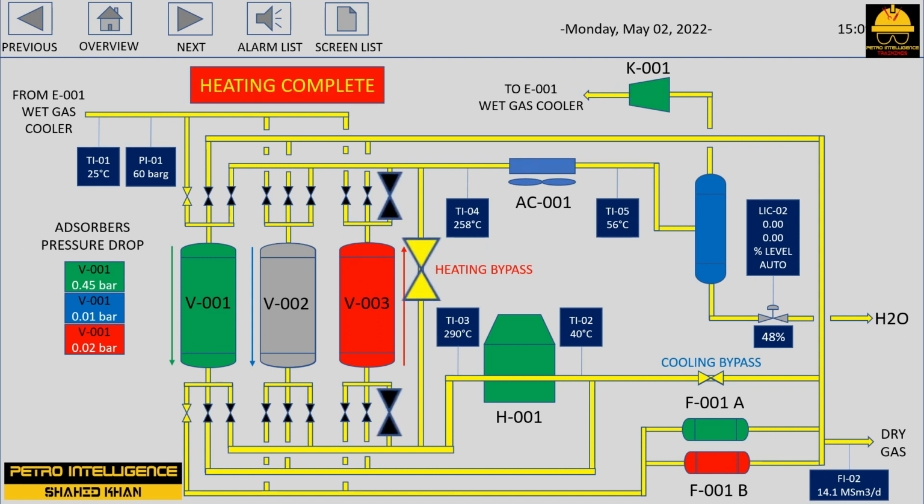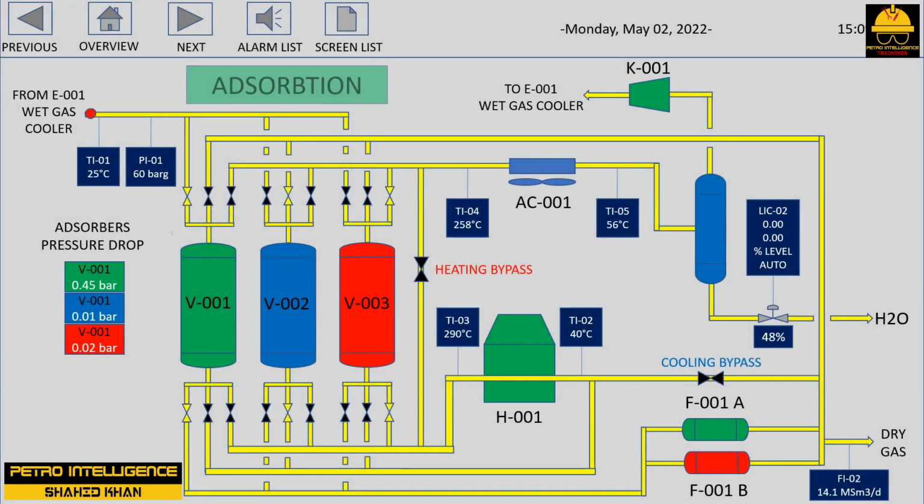There are also connections for treating the bed during the regeneration step. In ion exchange processes, there are generally two types of fixed beds. Single bed systems remove only one type of ions, either cations or anions. Two-bed systems remove both cations and anions. The type of bed used depends on the process involved and the desired quality of products.